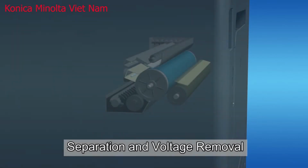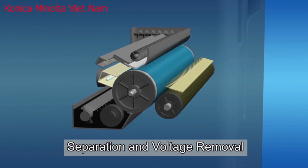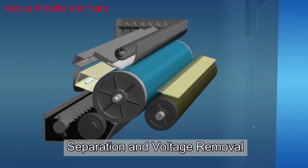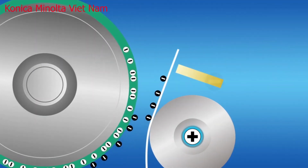The next process is separation and voltage removal. Here, using the curved surfaces of the drum and roller, copy paper is separated from the drum surface. At the same time, a minus high voltage is discharged to remove electrical charge remaining on the copy paper.